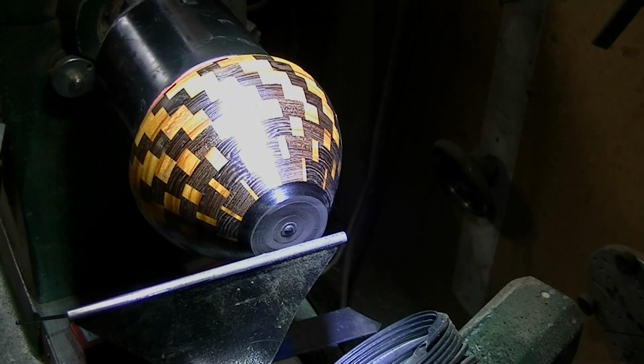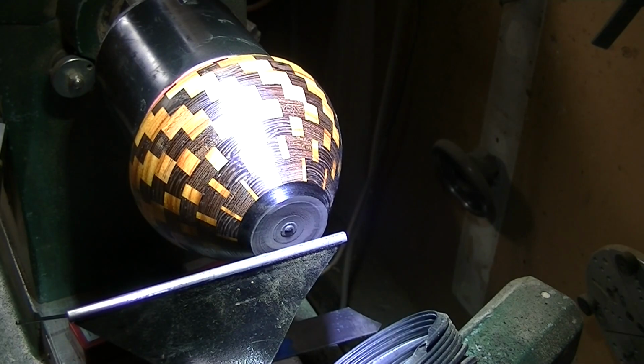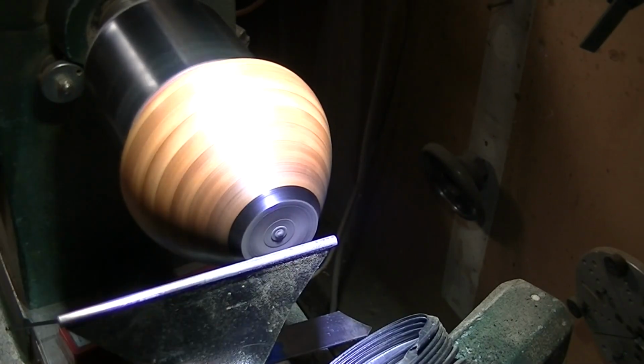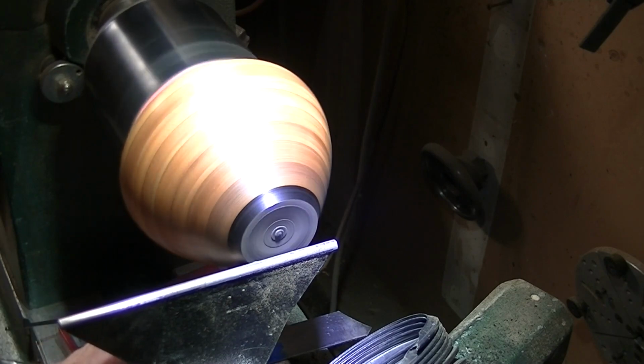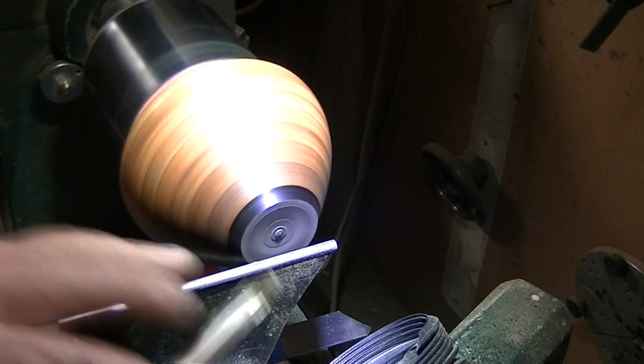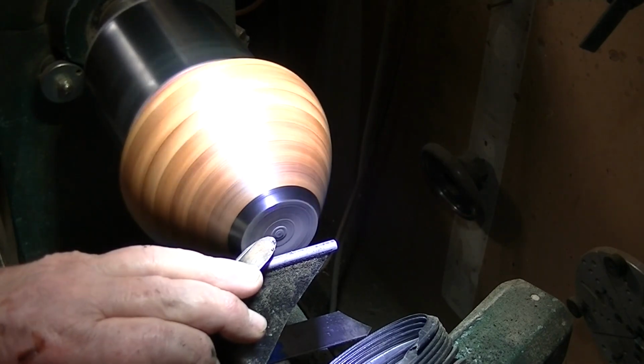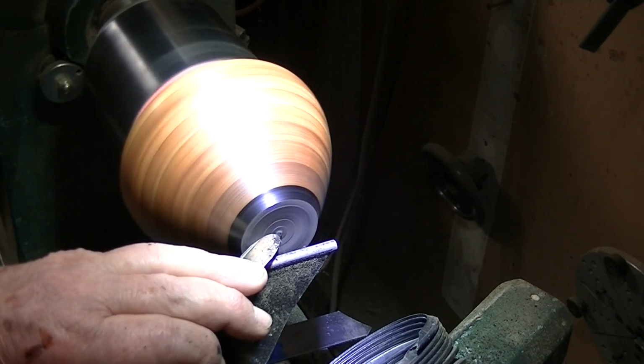So now we can remove the whole tailstock assembly out of the way. And there's still a little cleanup on the bottom to be done. You can see the marks left by the parting tool, and I want to cut all that away with a shallow fluted gouge and very light cuts. If I press across, I can easily dislodge the vessel from the vacuum chuck. So I'm not applying any pressure.